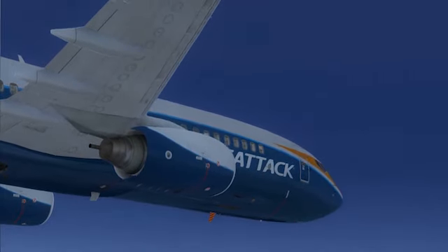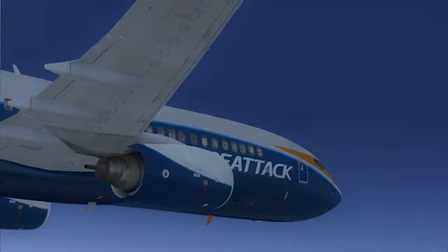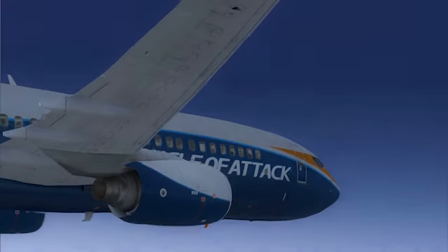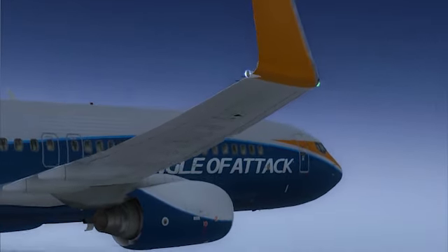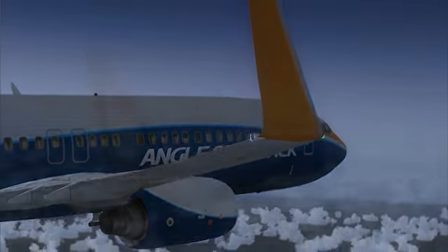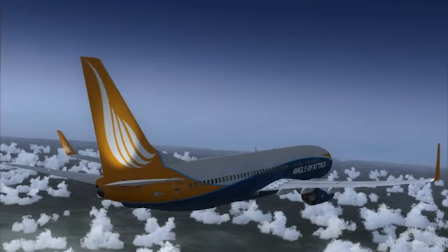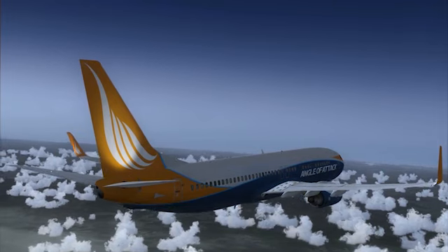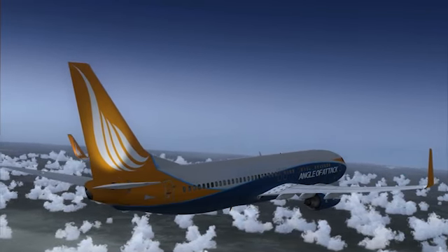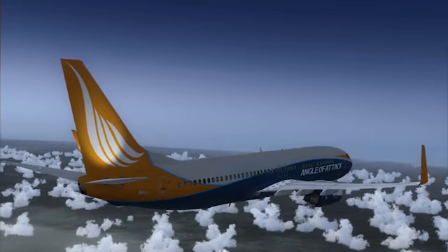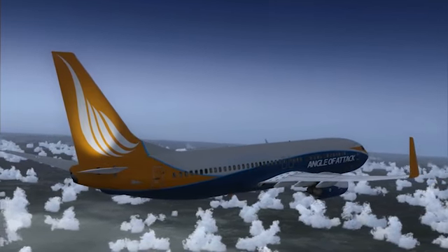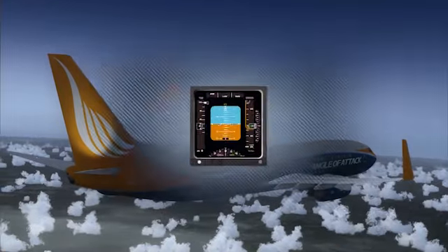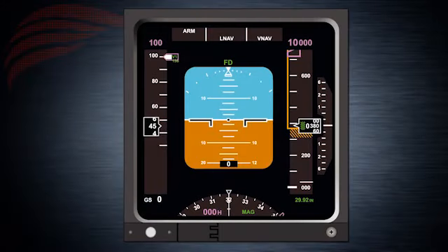The MCP's communication with the FCCs, and therefore every other component of Autoflight, is uniquely tailored for each flight mode that the aircraft is in. Each mode, as you look across the vast options on the MCP, has a different set of commands that the FCC sends to the Autoflight actuators, or displays to the pilots via the flight director and instruments. This system as a whole is useful to the pilot flying in different ways.